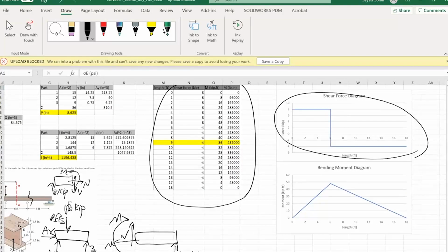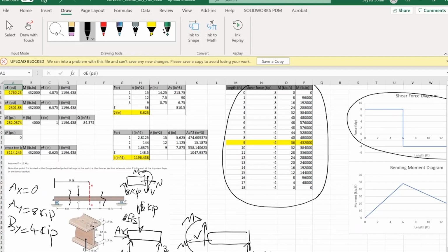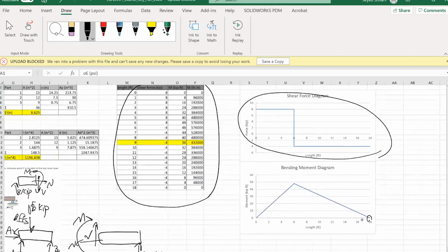You can think of the shear force diagram as the derivative of the bending moment diagram, and in order to determine the bending moment diagram, we know that at the two supports B and A, we don't have any reaction moments. Why? Because a roller support and a pin support would not be able to provide that. So we know that these two points are already zeros. We already know before we do any further calculations. And in order to determine the rest of the diagram, we can benefit.